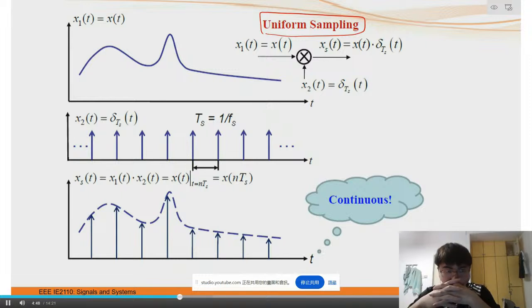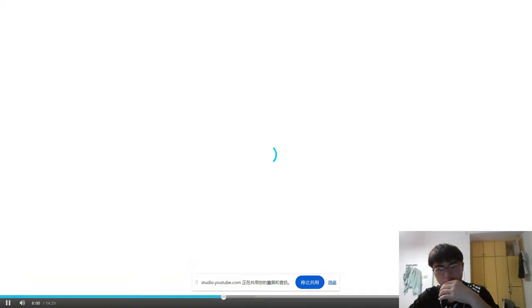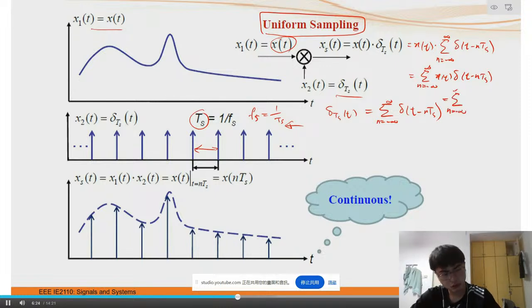In this case, essentially we are taking this signal, x(t), and multiplying it by another signal, which is a periodic train of impulse functions, sometimes called an ideal sampling function, as shown here. It can be written as a sum over n from minus infinity to infinity. You are evaluating the continuous time signal at that particular sampling instance, nTs, and then you get a set of delta functions, each of them weighted by the sample value, which is shown in this diagram here.